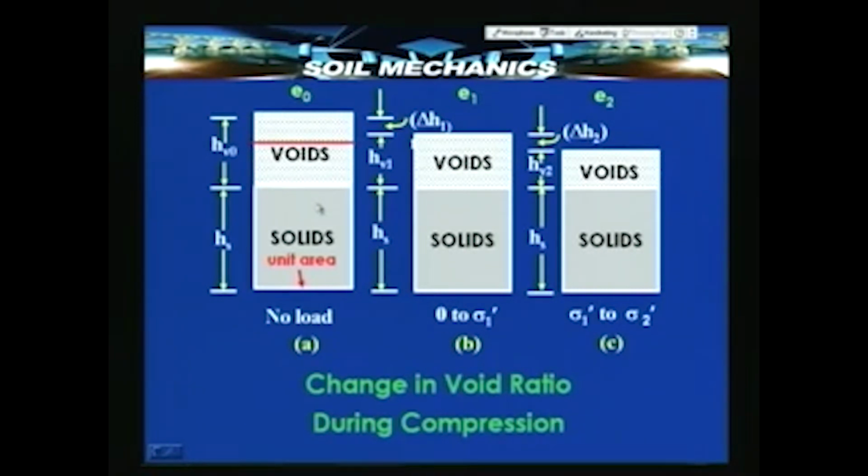Water particles are incompressible. So, it is only the air which undergoes compression. The only other way to compress is water flowing out, and let us say as the load increases from 0, that is no load, to an equivalent stress value of sigma 1 dash, then solid remaining constant, the voids decrease to a new height H V 1, there is a decrease of delta H 1 and the new void ratio